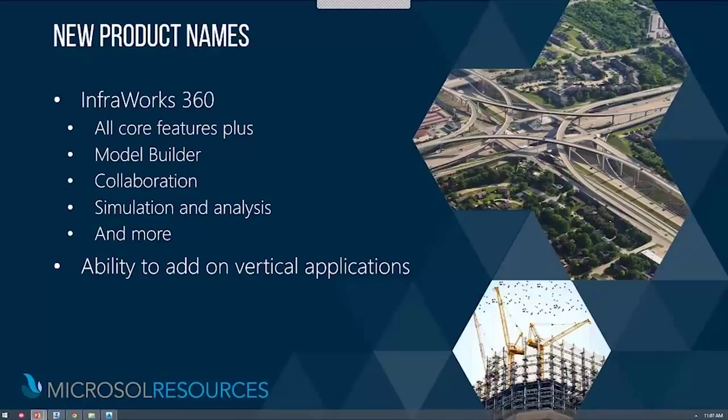The roadway module being able to engineer roadways, both from an engineering perspective, being able to set an alignment, being able to set a profile, as well as structural engineering for the bridge, being able to model a bridge based on a particular girder type, use some abutment objects that have been developed inside of a vendor, et cetera. And then last but not least, drainage design, which would probably interest nobody but a civil engineer. Those allow you to create some conceptual layouts for drainage utilities, such as storm and sanitary.